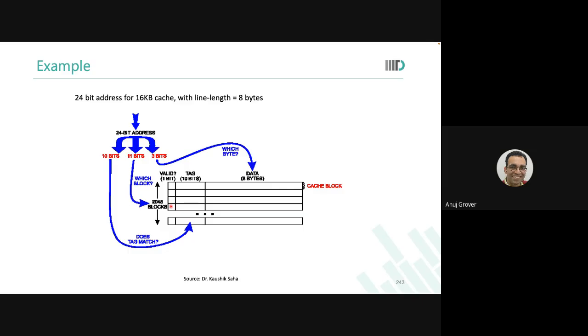So are you realizing that, first thing, we moved to a different level of hierarchy, a different level of abstraction than circuit design now. We're no longer talking about transistors, and we're no longer talking about RC delays per se. We are talking in terms of the total delay of a line access, but not exactly in terms of RC and transistors.